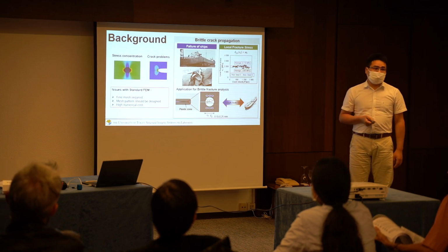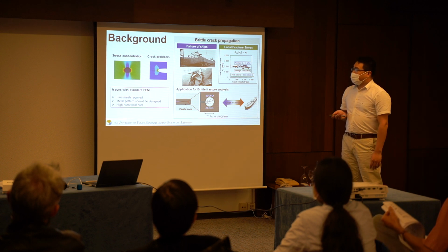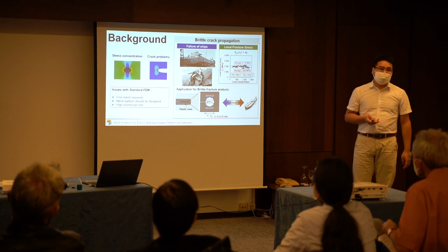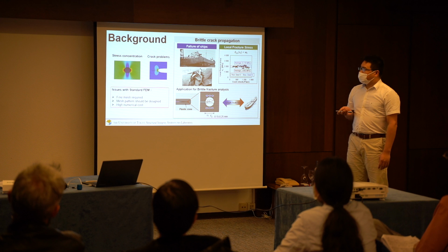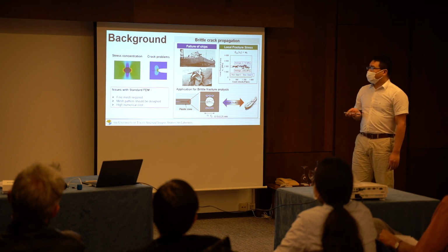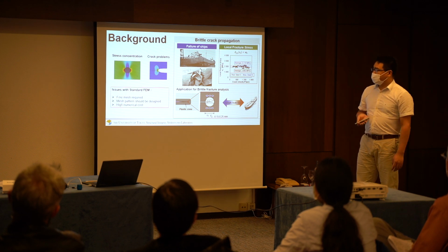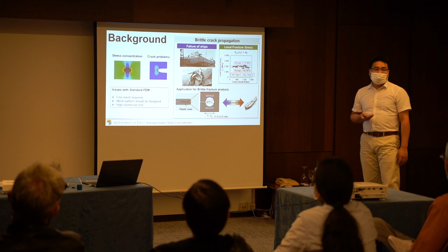The finite element method is a powerful tool for structure design and failure analysis. However, when it comes to stress concentration problems or crack problems, to get accurate numerical predictions, we need to reduce the element size or increase the shape function orders. However, that will increase the numerical cost.